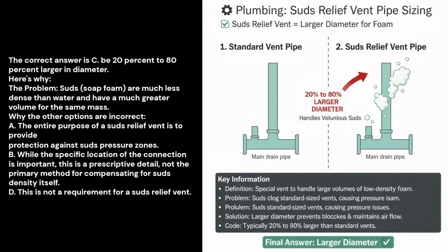D. Connect to each fixture trap. This is not a requirement for a suds relief vent. A suds relief vent is designed to relieve pressure in a branch or stack that is carrying suds from multiple fixtures, not to connect individually to every trap.